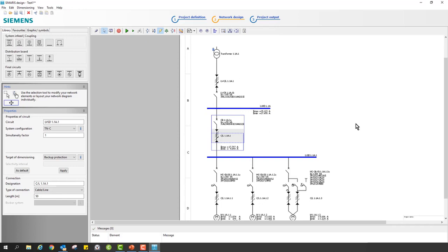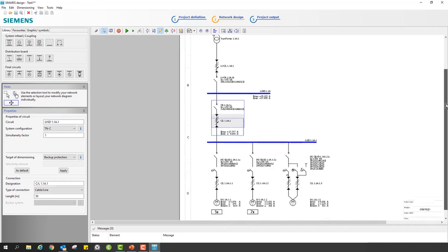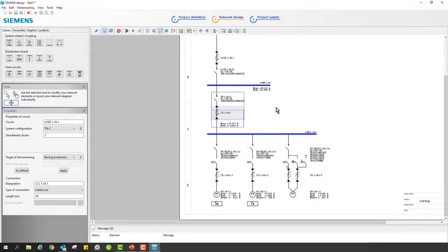one of the invitations for the event was, well, your customers always ask you for a control panel that complies with 50 kiloamps. But actually, control panels are not near the transformer. They are downstream in the installation near the machines. 50 kiloamps is usually used by EPCs and designers as the whole installation needs.